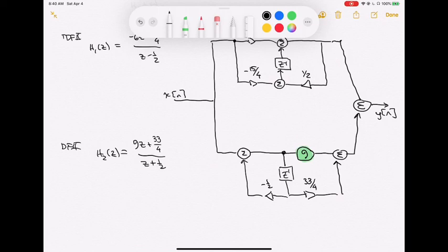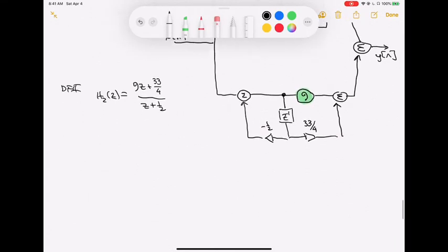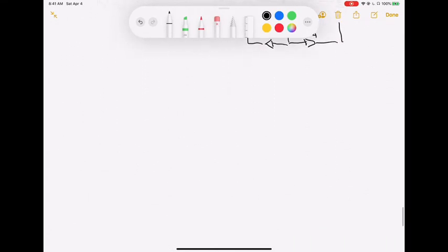So this is an example of taking that second order system, which happened to have all real roots, and breaking it up into a parallel realization. You can get that parallel realization in many different ways. This isn't quite a standard partial fraction expansion approach, but partial fraction expansions would usually be a very good way of doing that.